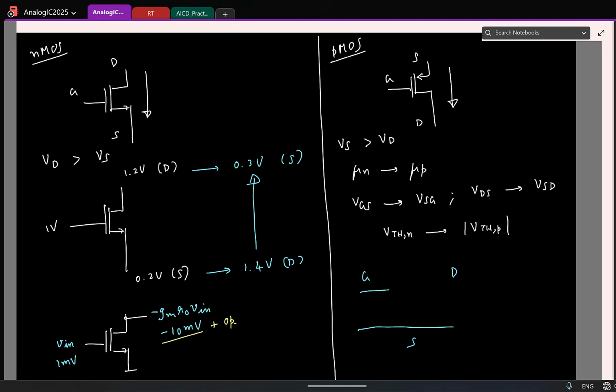I will have current flowing from what to what? Which terminal to which terminal? Source to drain. So I have the same voltage controlled current source, but the current will be GM times VSG in parallel with the resistor. Now of course, if I say that the current flowing up is GM VSG, what is the current flowing down? Minus GM VSG, the same as GM times VGS. Okay.